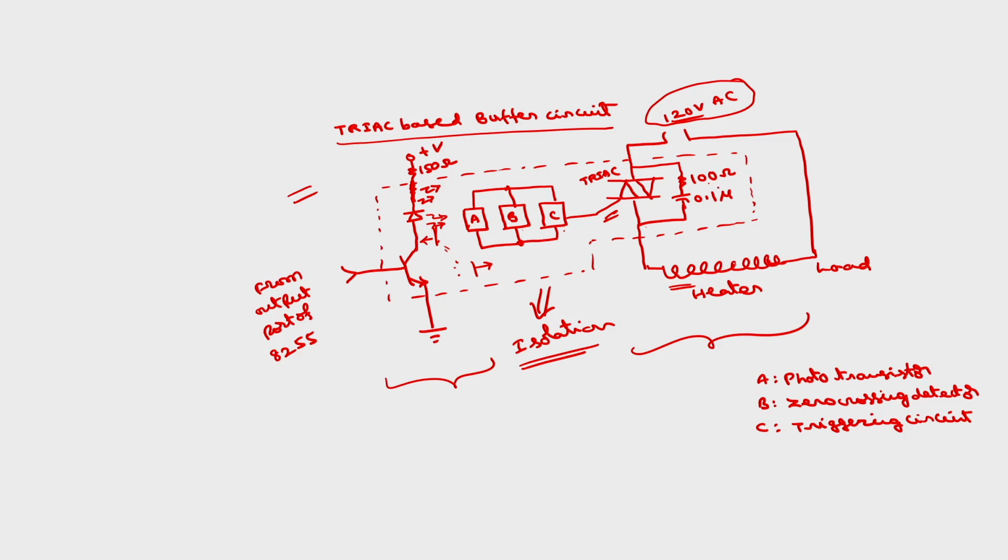So, this control circuit requires 100 ohms and 0.1 microfarads. See how we can drive a very large current with this one. We can have up to even 1000 amperes also. Depending upon the capacity of the heater that we are going to use here, we can design this circuitry to give that much current.